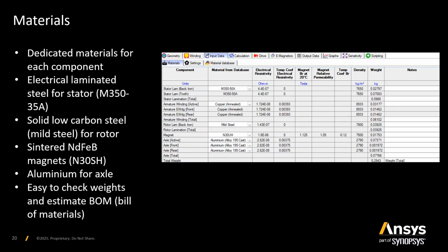Anticipating a potential question: how about the core losses in the back iron for this type of machine? Because the magnets are mounted on the surface without an air gap, typically the rotor losses in these machines are negligible, especially as the rotational speed will be only up to 5,000 RPM. There will be some induced eddy currents in the space between the magnets and just below the magnets sitting on the magnetic steel, but this can be well handled by the structure of the machine.